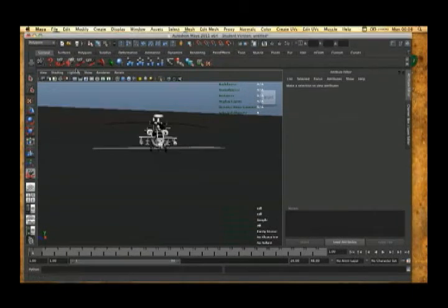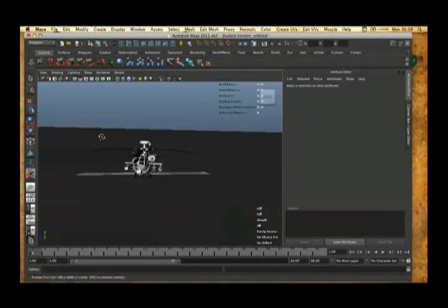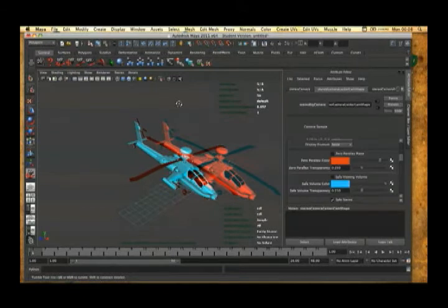We have the scene here. What I'm going to do is simply go through how you make a stereo camera. It's not that difficult, it's quite simple. You go to stereo, create stereo camera. Okay, so the camera's above it right now, but you can see this is looking through the center cam on the 3D camera. The center cam is normally used for viewing purposes, previewing purposes,